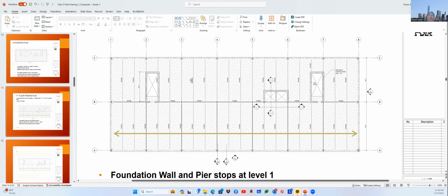And also the beams in the middle bay, we call filler beams, should be placed uniformly, in mostly typical cases. But the spacing of the beam, typically we use 10 feet. But 10 feet is not an absolute number. It's because of the metal deck and concrete slab above, based upon their capacity, we are able to choose those beam spacings. But typically, I gave you the 30 feet column spacing, right? I think it ends up with a great 10 feet uniform spacing of the beam. So this is very common practice.